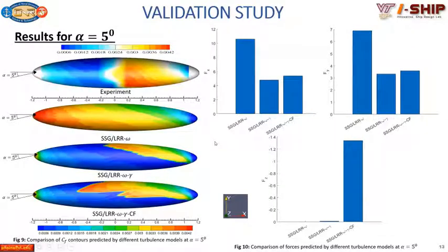Finally, coming to the lowest angle of attack. This is the case which is actually a little problematic, because according to literature, this case shows both natural as well as cross-flow transition. This complicates matters, giving a complicated contour, as you see here.